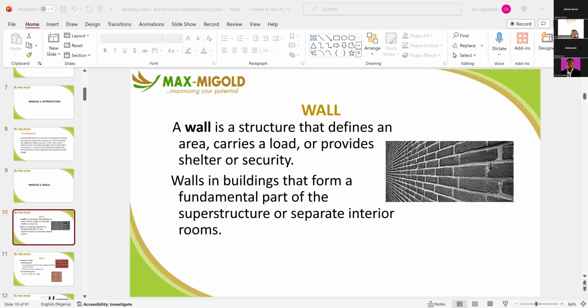Then finally, we have the pile foundation. These are the ones you use where the load bearing capacity is extremely bad and the load coming on that building is very heavy. So you need to drive the piles to a more stable soil or part of the earth crust underneath, where it can stably carry the structure and make sure the building doesn't sink. And that's just a way to look at the types of foundation that we have in a building.